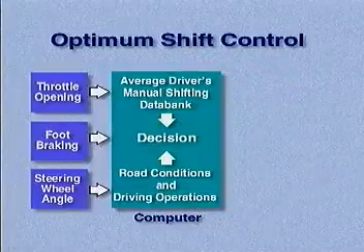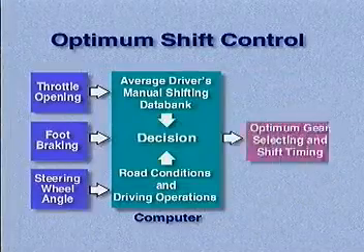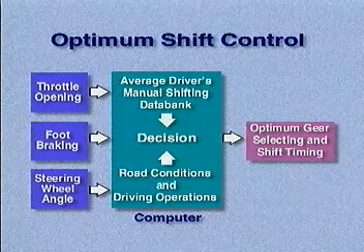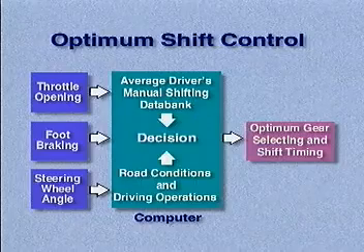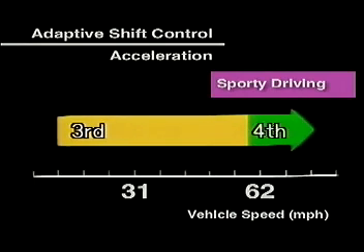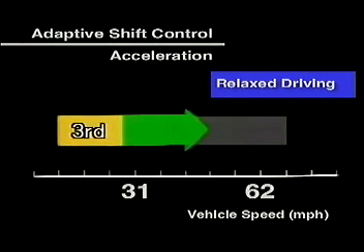With INVEX 2, feedback and learning capabilities are added to fuzzy logic to modify the transaxle shift pattern according to driver preference. As the INVEX 2 system learns a particular driving pattern, it modifies its shift control pattern to favor an aggressive sporting driving style or a relaxed mellow driving style.